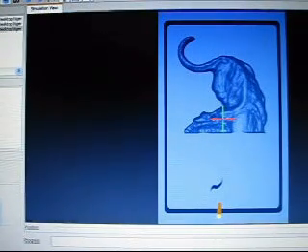In the Y dimension, we decided on like 5.5 inches. Your offset is going to be negative half of that, so I think it's minus 2.75. In the X direction, I finally decided I'm going to use a piece that I have on the table right now. It's 3 3/4 inches, so I'm going with the 3.75 inch stock.